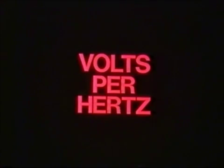This type voltage regulator is classed as volts per Hertz regulator. By varying voltage with frequency, this type regulator will tend to eliminate the problems of under-frequency operation as associated with voltage sensing only units.